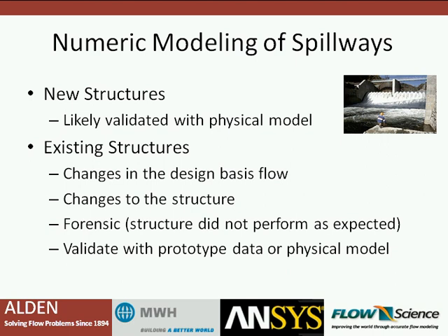And there we use CFD to first model the existing condition and then model proposed conditions or proposed modifications and see how those are going to work. Other areas where we've used CFD on spillways has been forensic type applications where a spillway might not have quite performed the way as was expected.